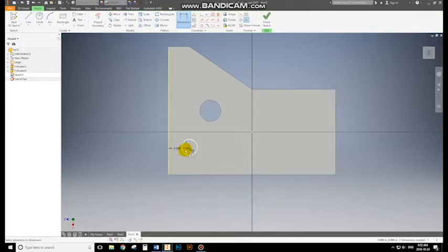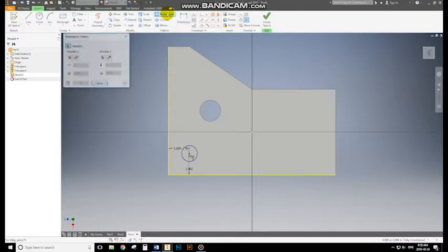Drawing lots of shapes in our sketches can get repetitive. The pattern commands help us make lots of shapes using less effort. We can draw lots of shapes in a rectangle, circle, or mirror patterns. Using the rectangle pattern, we can select the shapes we want to replicate, lines in the direction we want to make our pattern, how far apart our shapes should be, and how many shapes we want in that direction.